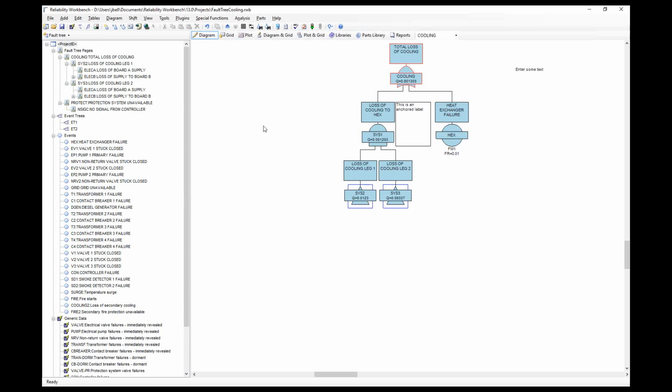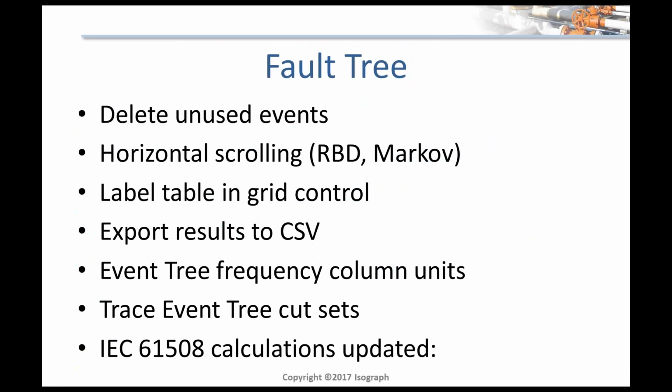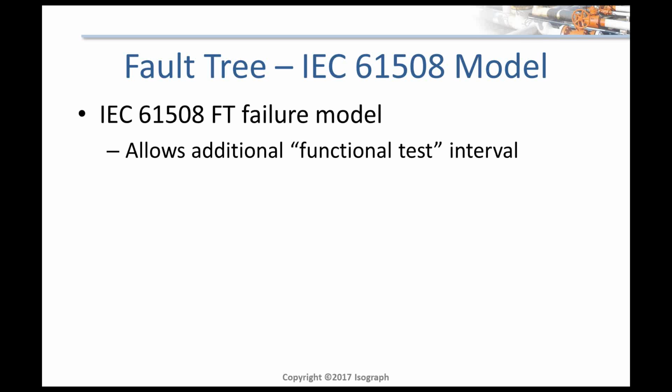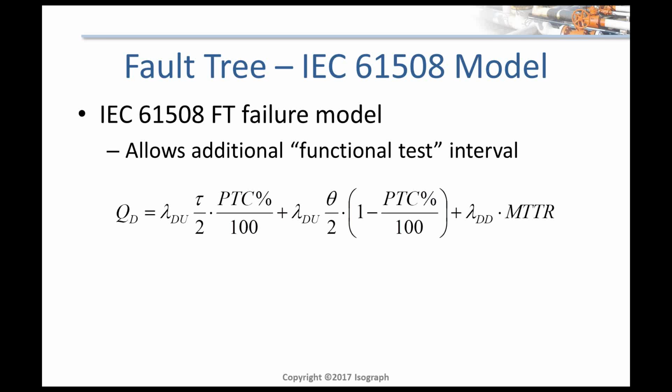Okay, so last thing is there's been a number of changes to the IEC 61508 calculations in the software. The first one is a new failure model. We've updated, or actually not just updated, added a new 61508 failure model. This one is called the IEC 61508 FT, or Functional Test Model. And it allows an additional functional test interval.